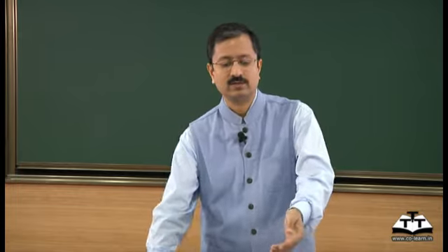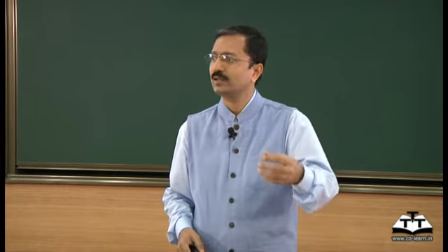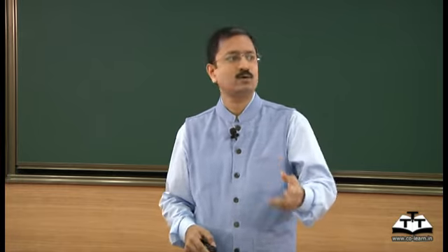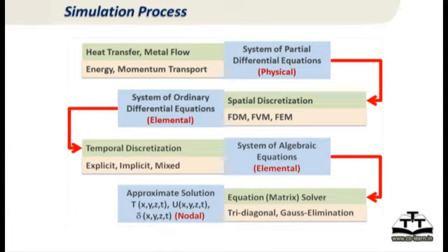First, the black box contains the fundamental equations for your mass balance, energy balance, momentum balance and so on. Those equations, number one. Number two, they convert those equations into a system of partial differential equations which are solved after you discretize. When I say discretize, you divide the space and divide the time, both into smaller steps. And you solve those systems of partial differential equations.